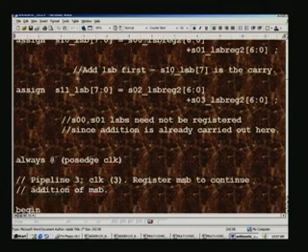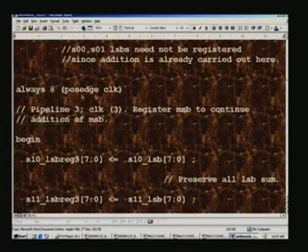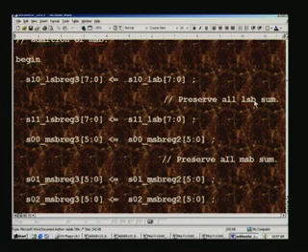of the first stage, and we designate them as S10 and S11 as far as the LSB sum is concerned. This is the LSB sum, and naturally there will be a carry resulting here, which will be added with the MSB later on. Now when the positive edge of the clock is encountered, that is at clock 3, we register the MSB to continue the addition of MSB later on, and we also have to preserve this LSB sum because we need it at the end, and that is what we have here, S10 S11.